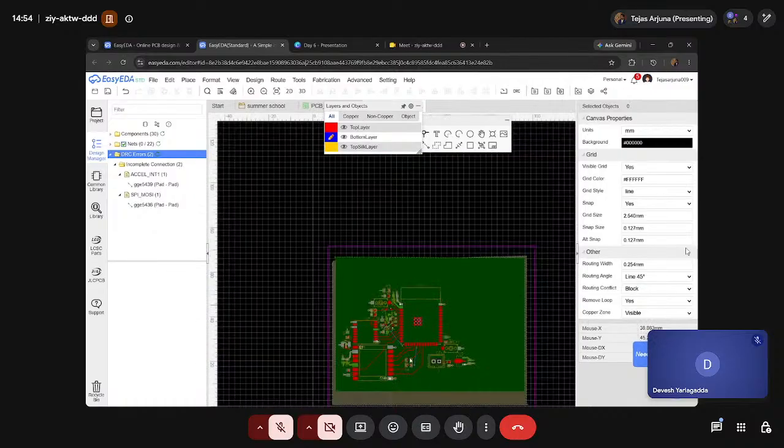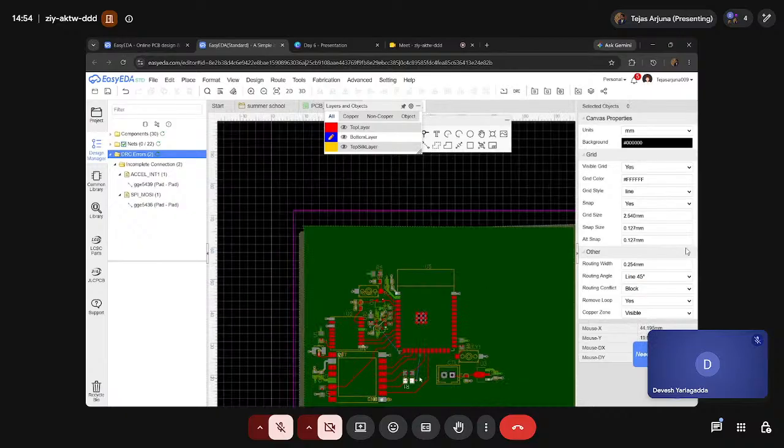The thing is, we could have made the VDD connection here itself. But why didn't we make it? We can't make it in the bottom layer because the SMD pads are on the top layer, so we can only make the connections in the top layer. Why we didn't use the top layer for VDD connections is because we don't want larger loops.